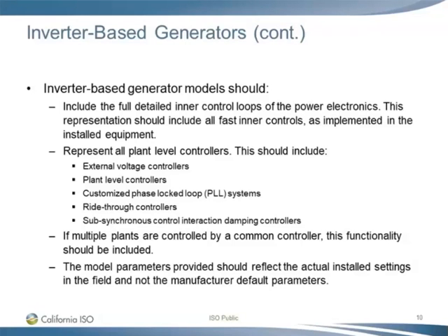If multiple plants are controlled by a common controller, then this functionality should be represented in PSCAD. Additionally, the model parameters should reflect the actual installed settings in the field and not manufacturer default parameters. Next slide, please.